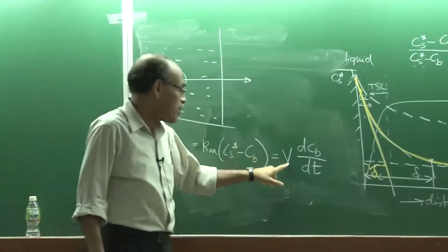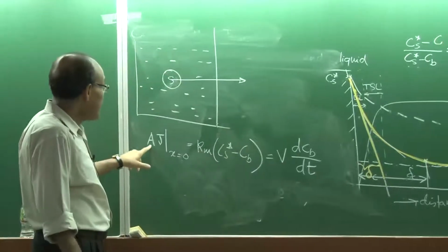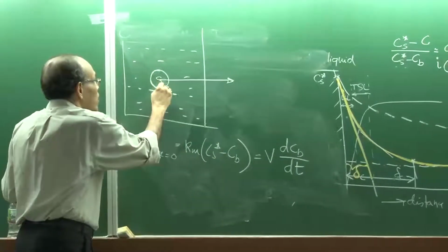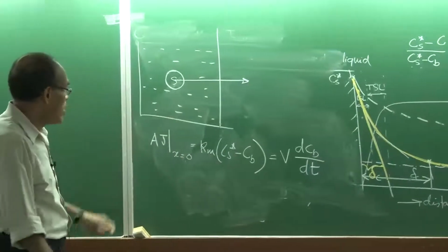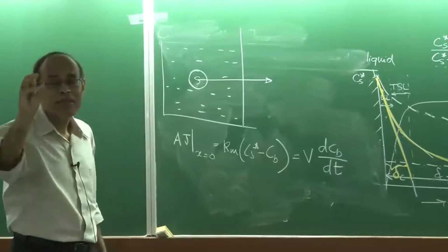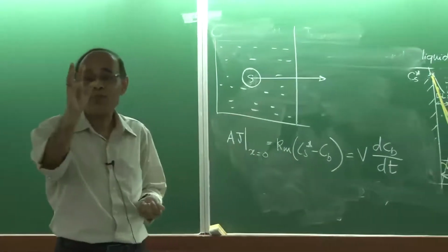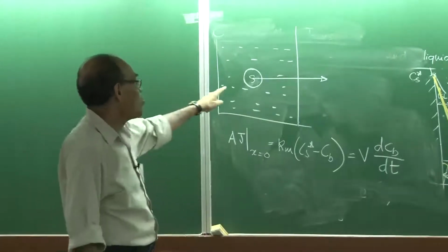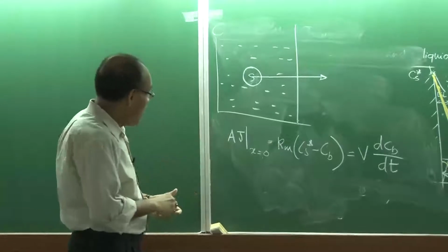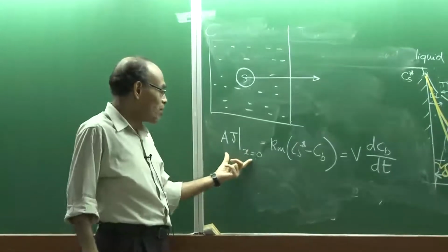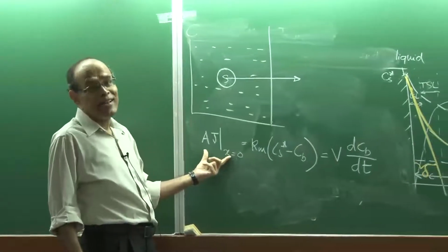And V represents here the total volume of liquid contained in the system, and A represents the interfacial area, or the area through which the mass transfer takes place. Note that as dissolution takes place, or the solid is progressively dissolving into the liquid, the size of the solid is also changing, as a result of which this area is not going to be constant. So I could say that this essentially represents the initial instantaneous rate of transport.